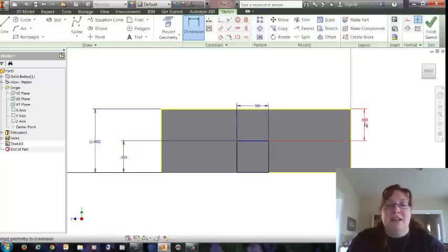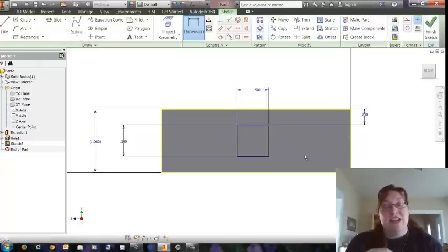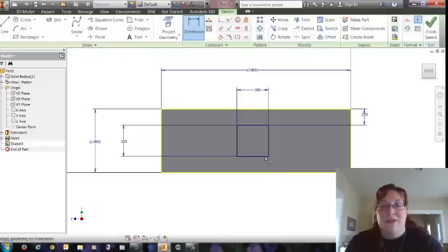So I'm going to come here and I want to put this in the center, right? So if I put it at 0.5, what happens? Notice it centers my box down 0.5, which puts the edge of my rectangle half an inch down, which isn't where I want it. I want to center it. So I want to put it half of a half, which is 1/4 of an inch, 0.25. So there we go. Now it's centered down.